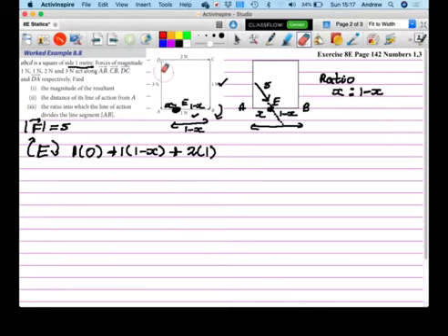So we're taking moments about A, and it's going this way. Its perpendicular distance is x. Now, as you can see, because it's coming down here, it's going to have a turning effect which is going to go against this arrow, and therefore it's going to be a negative.